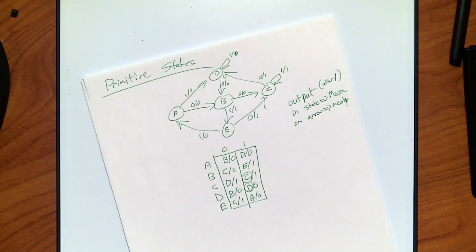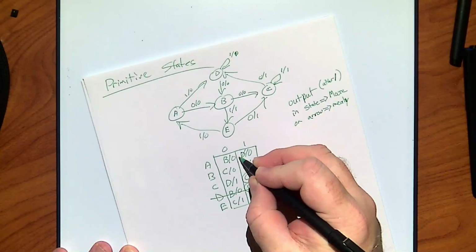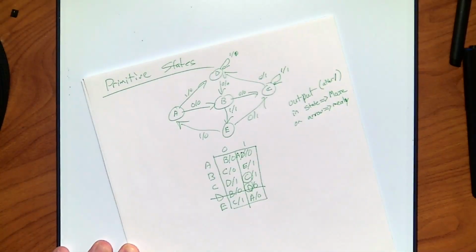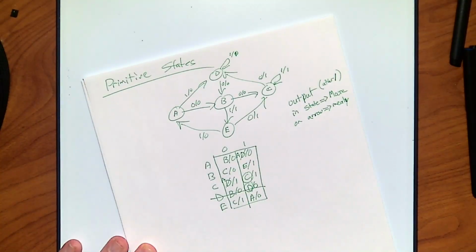Let's go on. So I can get rid of them. I can see on this chart, boom, I can remove one of these rows. And since A equals D, I can just remove D, and I just change this to an A, and I find any other occurrence of D and I make it A. We redraw the chart, and you will get indistinguishable behavior, but with fewer states.